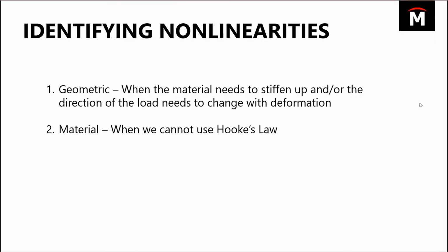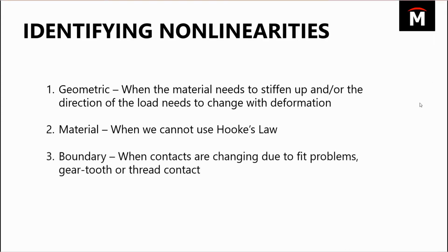And then the third one is something that can be a little hard to figure out. So I hope to show you an example of this in action, and that's the difference in contacts. When two items are contacting each other, and that contact area changes a lot over time. If you're really developing your own threads, threaded connections can have this. Certainly gear teeth, when they connect together, have a complicated contact area that's changing as things move in the simulation. So we'll look at some hands-on examples of that to give you an idea.